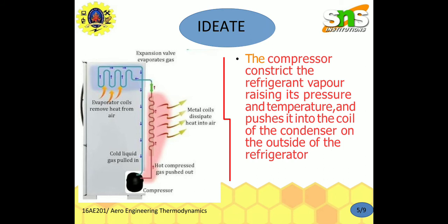In a gas cycle, the working fluid is a gas that is compressed and expands but does not change phase. The refrigeration cycle is called a gas cycle. Air is most often the working fluid, as there is no condensation and evaporation intended in a gas cycle.